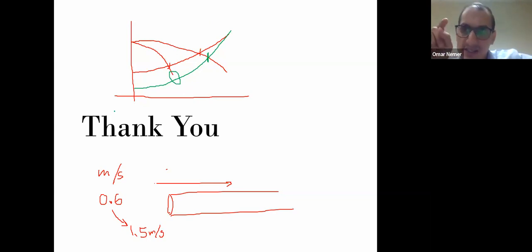You will notice the overload will make it trip. Unfortunately, sometimes when people see this trip, you know what they do? They put some wood piece or something below the overload to stop tripping. And what will happen? The pump will be burned.